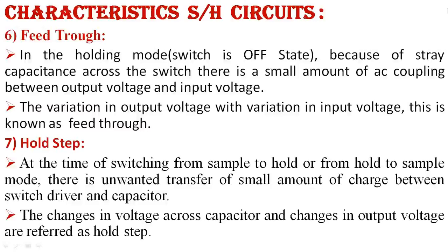Now next, hold step. At the time of switching from sample to hold or from hold to sample mode, there is an unwanted transfer of a small amount of charge between the switch driver and the capacitor. The change in voltage across the capacitor and the change in output voltage are referred to as the hold step.